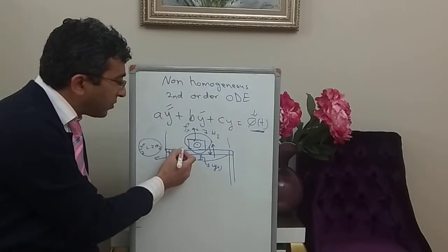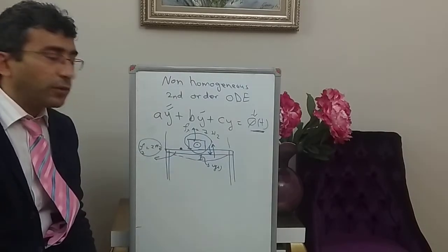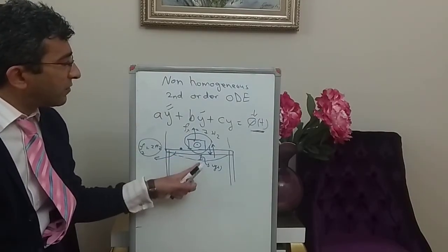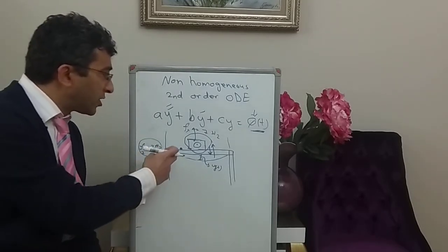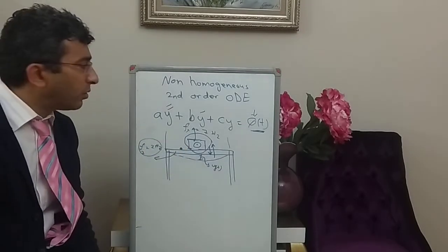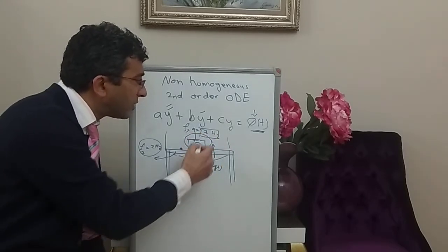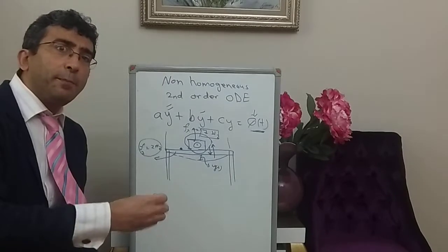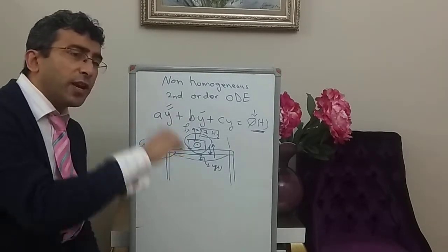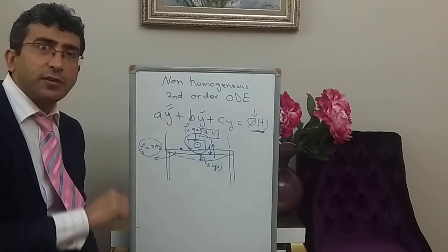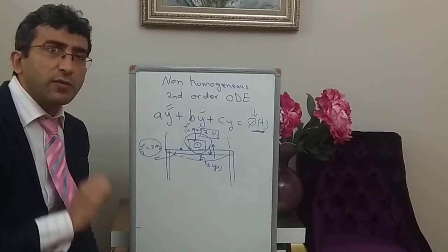If you put a sensor here, an accelerometer or a velocimeter, and you make an experiment and measure this vibration, then look at the frequency content, you will find the most important one is 7 Hertz. It means that your slab will move with the machine. You act on it with 7 Hertz, and it will vibrate with a frequency of 7 Hertz.